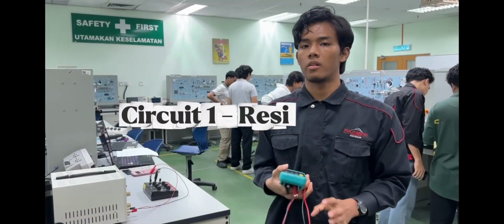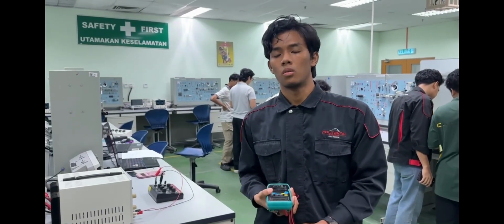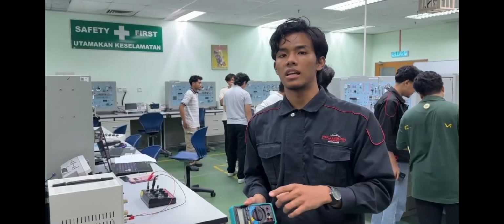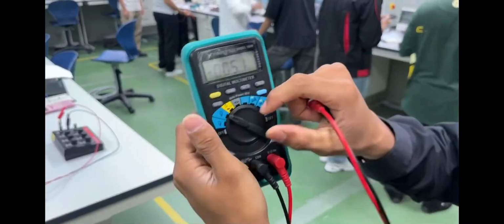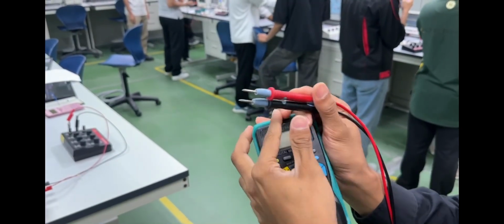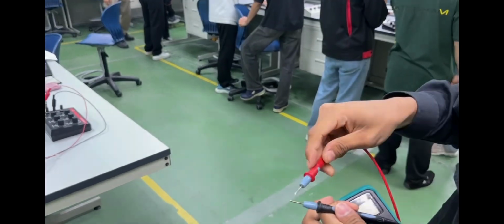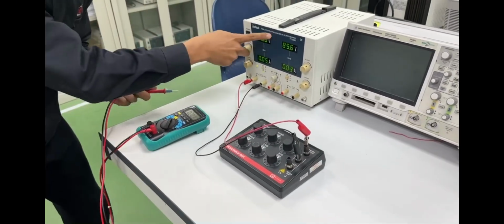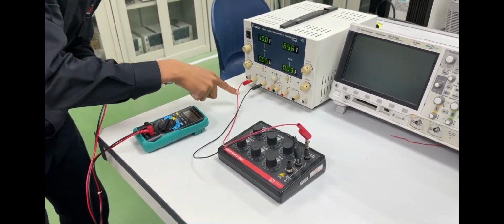Okay, bismillahirrahmanirrahim. So for the first circuit, we need to measure the voltage and current and the resistance. Before we measure the voltage and current and the resistance, we need to calibrate first. Like this one, and then the probe need to touch each other like that.